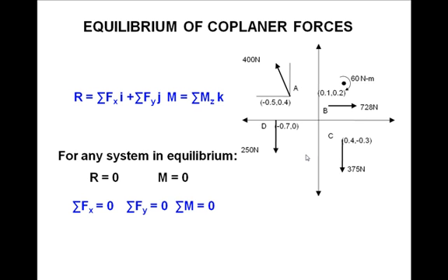So therefore, these three, sigma Fx equal to 0, sigma Fy equal to 0, sigma M equal to 0, form the equilibrium equations for a coplanar non-concurrent force system. And by applying these three equations, you can literally solve any problem, as long as, of course, there are only three unknowns to be evaluated. We are going to do a lot of problems on equilibrium of coplanar force systems in the next videos. But before that, what is required is some knowledge about the types of loads and supports, and that is here.